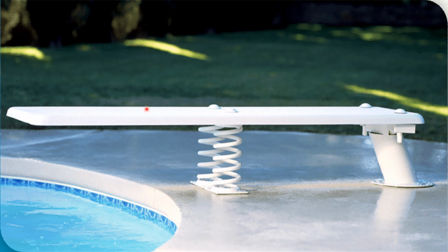If you had a very heavy person and the springboard was very flexible and the springs were very light, then this thing would flap all over the place and would not be a very good springboard to jump against. Somewhere in the middle, depending on the height or the weight of the person jumping on it, is the loading of that springboard, and hence the loading onto your counterpoise or ground or radials. That's very important, that the radiating element actually needs something to work against, and that's the whole concept of grounds. We'll get into this more in future podcasts.